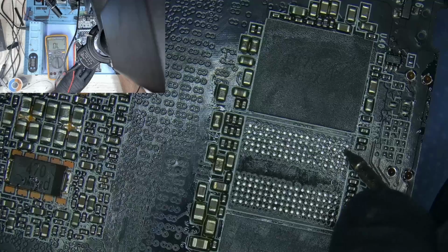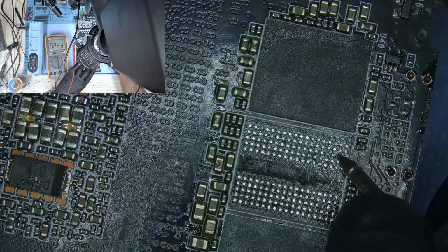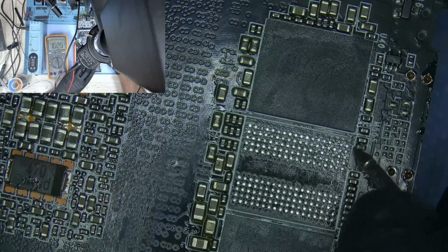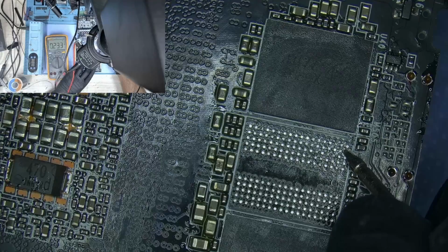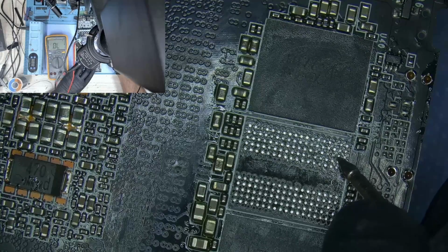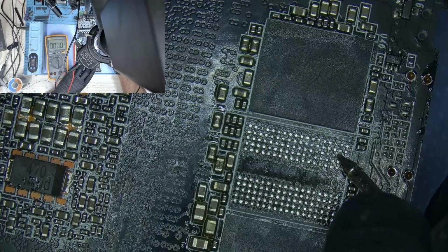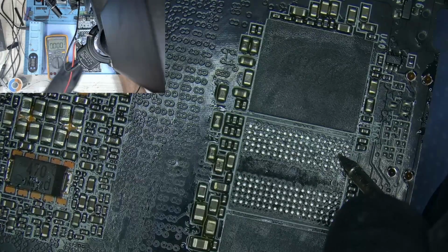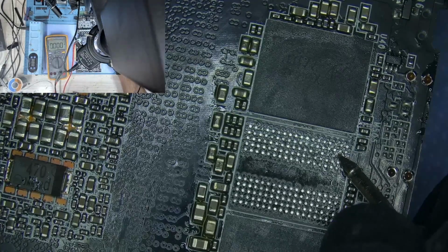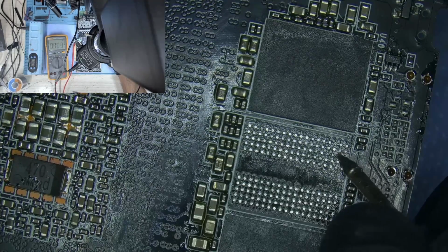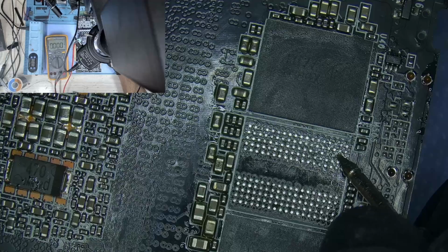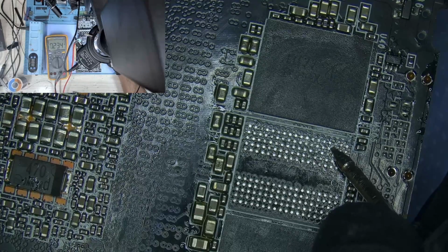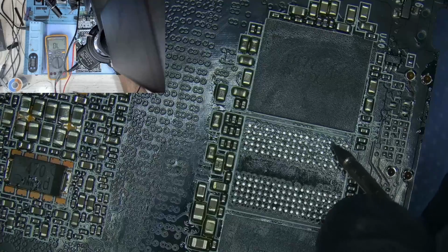Okay, there you go. We can see a short on one of the data lines. There you go, that's a short. So I wonder if the short is coming from the other side of the board, or is it coming from the GPU core? I assume it's from the GPU core, and it's not from the other side. But this is definitely a short on the data line. So the data line is shorted to ground, which is not a good sign.